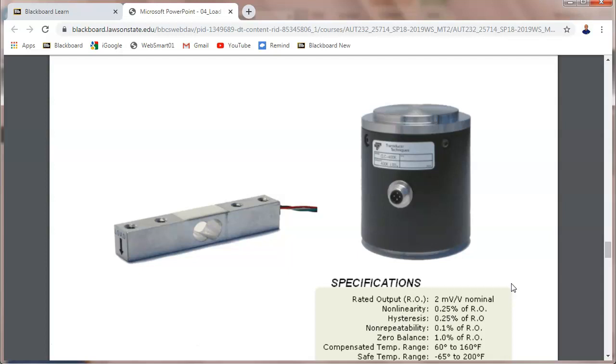This is another type of load cell. And what would happen is your strain gauge is actually mounted up in here. And what you do is you make one side permanent, and then you make your load side. You can actually see the load on this side. And when you put a load on it, this thing would warp. And it would cause the strain gauge to do what? To warp and change its resistance. So we had all types, different types.